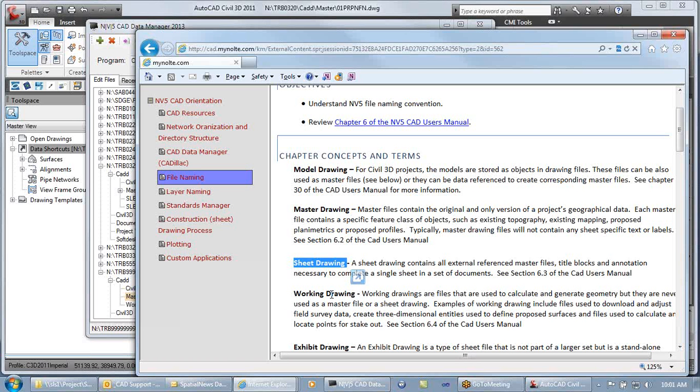And the reason I do it that way is that way on a larger project, if I've got red lines and I've got 20 sheets, I can have 4 or 5 people working on different sheets. Whereas if you had all of them as layouts in a single drawing, I can only have 1 person editing that. Okay, and also by going to multiple drawings with 1 sheet per drawing, we can start using things like XREF clipping, surface masking, and things like that, where we can control with great precision how much information is displayed within that sheet. Whereas when I start doing multiple layouts, well, I can't XClip because what I clip for one layout is going to mess up the other layouts.